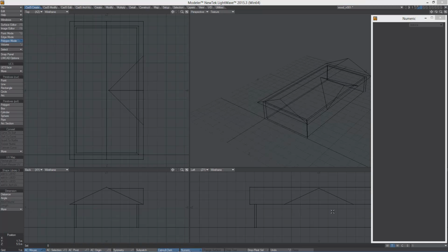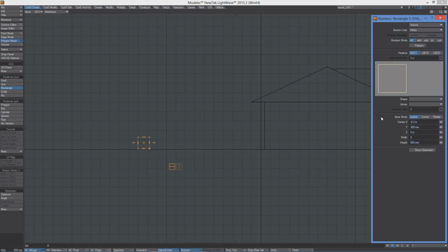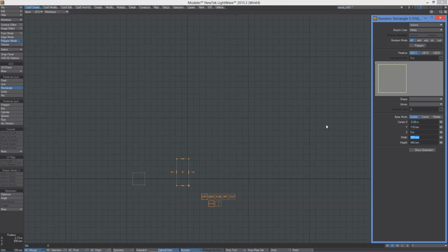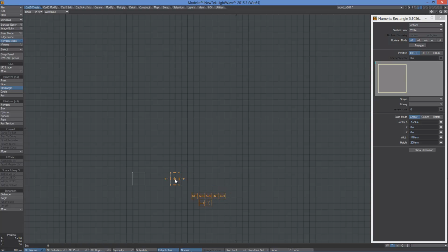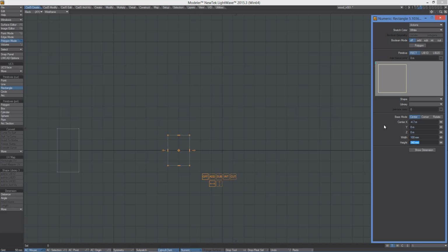In the second step, we create fully UV mapped wooden objects of beams and planks. So first we will create profiles in back viewport using the rectangle tool. Just set the size of the profiles. First two will be beams for the wooden structure, and the last one will be the plank, which we will use for covering surface. So it will be a size of, let's say, 5 or less.